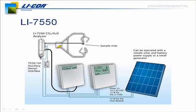So now if you are making flux measurements, you can take the analog outputs from any typical sonic, whether it be from Campbell Scientific or Gill or METEK, RM Young, any of the common sonic anemometers with analog outputs can be brought into your 7200, and we can time synchronize the data collected so you can get your U, V, W, sonic temperature, CO2, water vapor, diagnostics, all time stamped and synchronized together. So that's another nice feature of this new instrument, just being able to get that data put together quickly and easily.